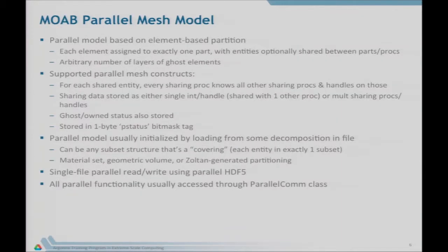Okay, so MOAB's parallel mesh model is based mostly on an element-based partition where each element is assigned to exactly one part. It supports an arbitrary number of layers of ghost elements, and I'll get to some code that shows how you do that programmatically in a few minutes. It also supports various parallel mesh constructs.